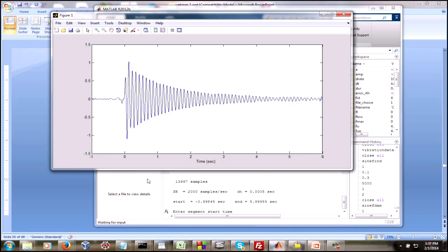So one very simple way is to count the number of peaks and divide by time. And if we go from 1 second to 2 seconds, you'd find that there'd be almost 10 positive peaks. So this signal is going to be about a 10 hertz damped sine signal. Just a couple of things more about this. When the vehicle is bowing downward, while it's still attached to the L1011, it's in a static deflection shape.